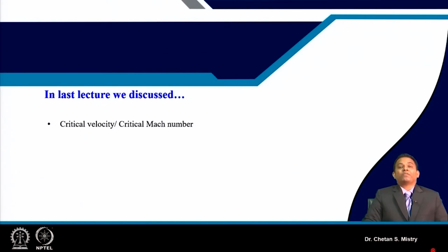Based on that, we need to decide the diameter of my casing, the diameter of my hub, the height of my blade, the chord of my blade, and how my flow angles will be varying. We have different approaches for the design of the blade from hub to shroud, and that is how we do our iterations. Finally we reach some shape of our stage for rotor and stator, and that is what we have defined as the sizing problem.